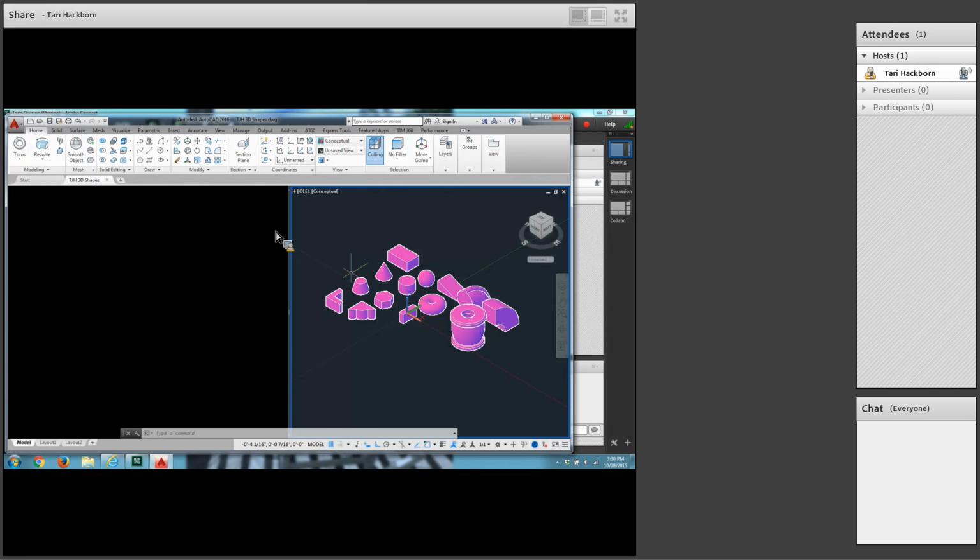Okay, next, using chamfer and fillet on solids. Okay. If your UCS symbol, see like mine here, ends up someplace it's not supposed to be, type UCS and enter twice. UCS, enter, enter. There. That gets it back where it belonged, down here in the corner.